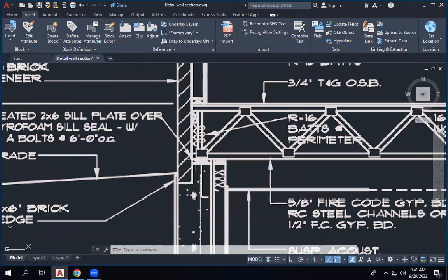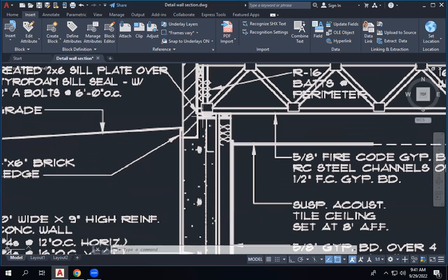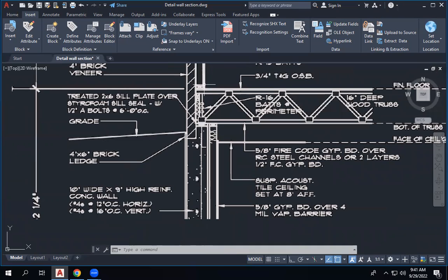So you just draw this one. See here, now they have stopped it here. The concrete wall is like this. They create a ledge here. So what they did was the truss is supporting on the concrete. See here, now the concrete wall is stopping at this point. What actual construction does is you will do the concreting up to this point. You cannot do it like this. You do it up to this, and you remove the formwork and do a partial thing like this. Otherwise, you have to keep a timber section here to avoid making the concrete here. So you cannot do it vertically. You put the two formwork and finish it off at this point. And after removing the formwork, you will have this piece, because then you can have a small timber piece on both sides and you can put the concrete there. Because this is not only one place, this is continuously heading from one end to the other.